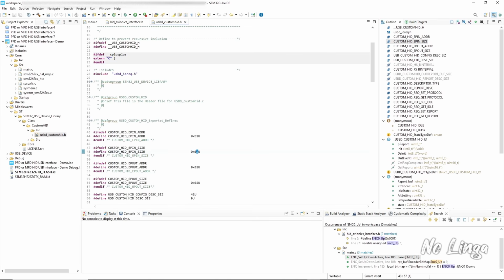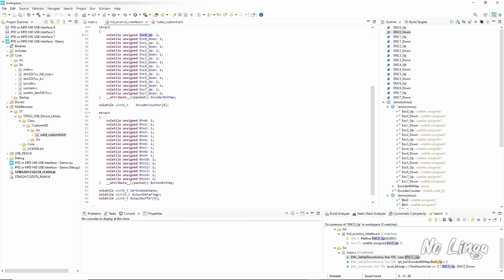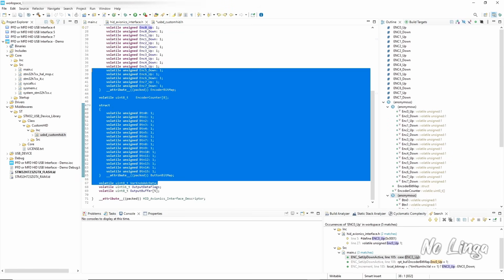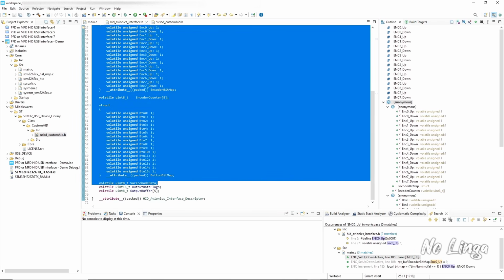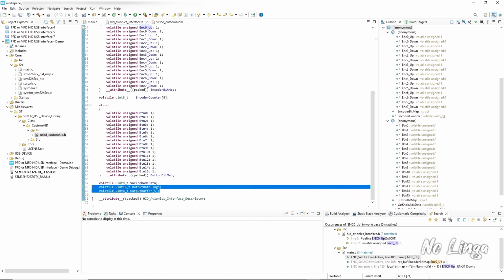So with mine, I changed mine to D because they're 13 bytes we're going to send, and this is in hexadecimal. So remember, the first 13 bytes we're sending in my structure here. So that represents the bytes I'm sending based on the functionality that we're implementing right now. And then these 7 bytes are the output. So when we read data from the computer back to the board, we're using these 7 bytes right now based on how I define the HID descriptor, and we'll go over that.